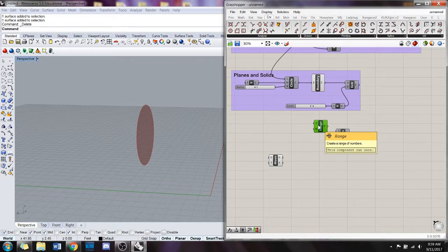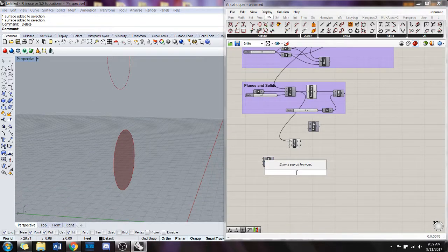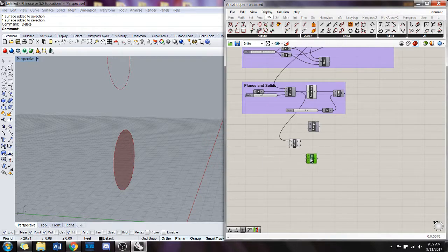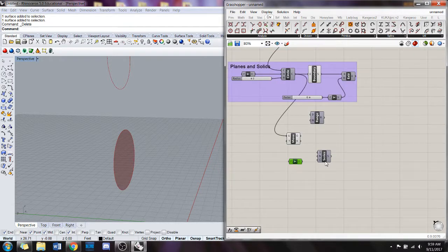So we're going to step it like we will in the assignment to create whether it's a floor height or a set of ribs on a bridge, which is the assignment for this week. We're going to take the circle and plug it into the geometry. We're going to just use this y vector, actually better yet, we're going to create a series. So we're going to give it a start point. It's going to default to 0, which is fine. Give it a unit y as the direction.